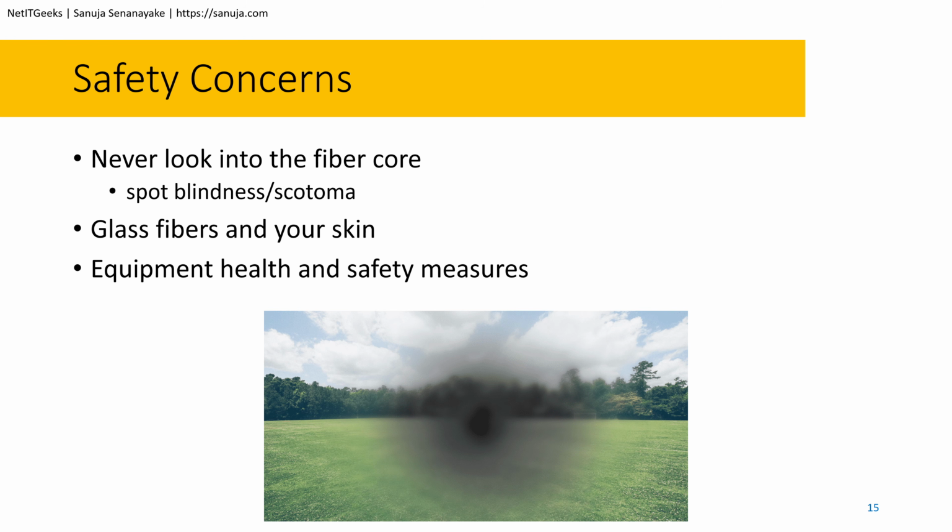So if you look into that cable, you may not notice that the cable is turned on, but it could damage the back of your eye. And what is that going to do? It is basically going to burn the visual cells in your eye, and as a result this type of situation could happen, where you will have permanent eye damage with blind spots in the back of your eye, and that cannot be repaired.